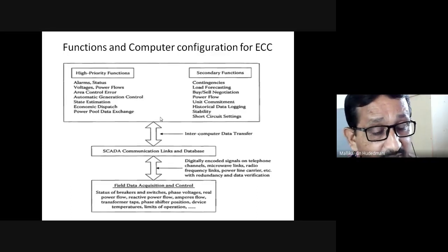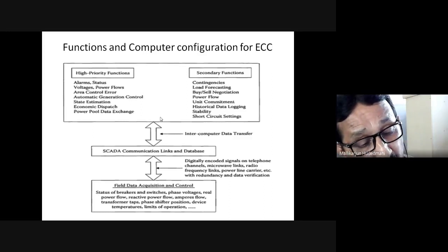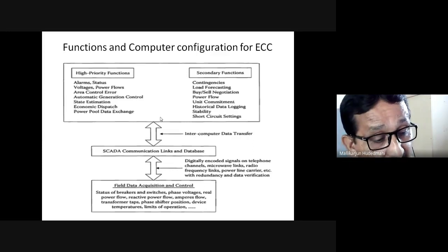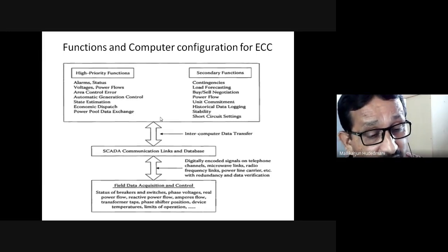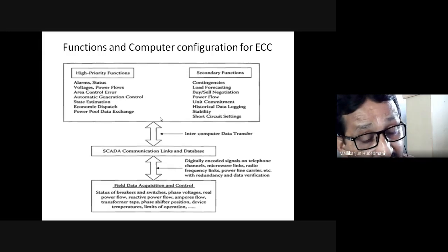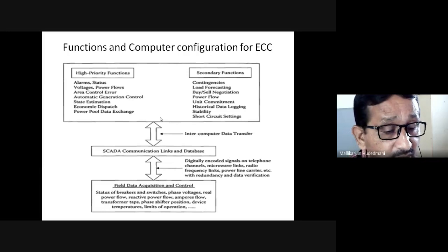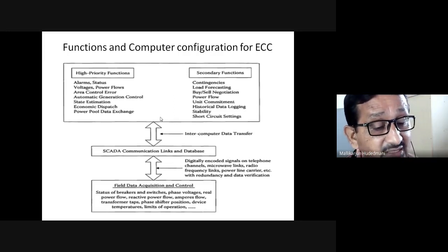If the transaction between district number 1 and 3 is going through district 2's transmission section, why should district 2 be informed? It is to be informed because the power flow is affecting district number 2 also. Even though it is healthy, a fault at district number 3 or district number 1, which are interconnected, gets propagated into district number 2 because of interconnected operation. When all become parallel, definitely cumulative effects will be there in the system.